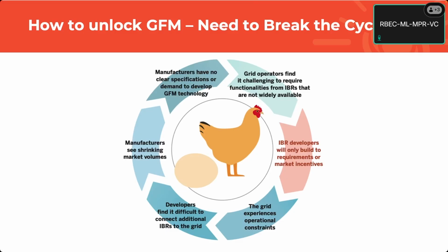If you don't have it, fine. So in that case, they'll have to procure extra to make sure they have enough, but they have all of this sort of available capability. But you're not wrong, and you can actually pay for extra capability if you want. If you want to make a market that says, we want you to maintain headroom so we can count on your inertial response or your frequency response, you can pay for that, and that's what they did in Great Britain.